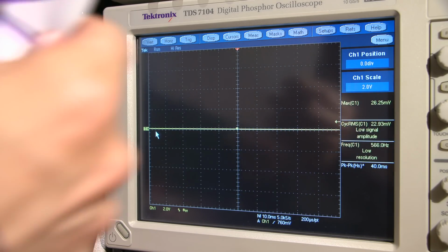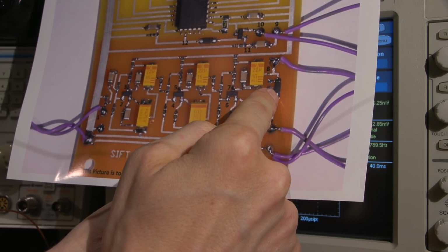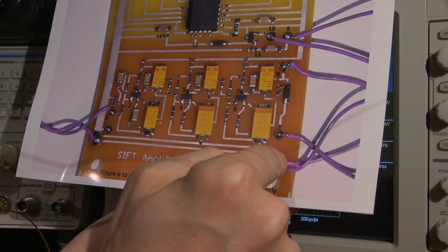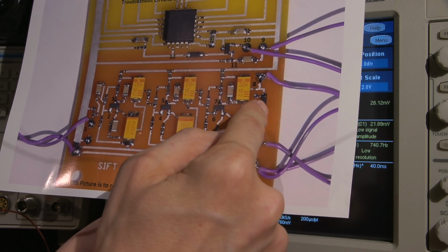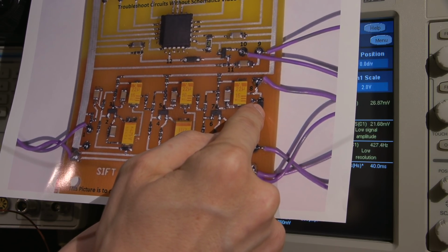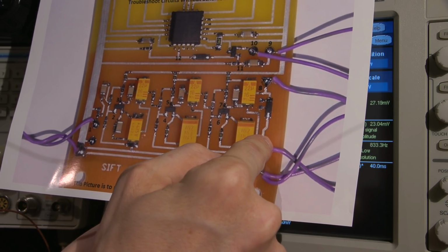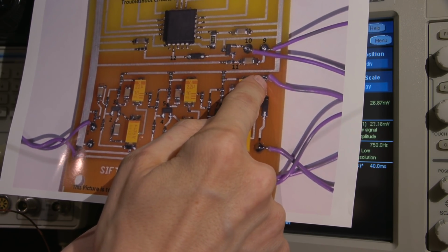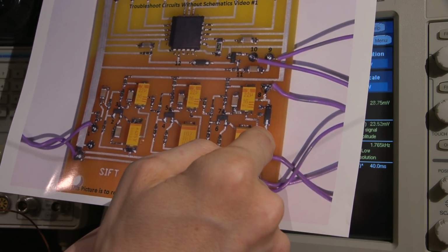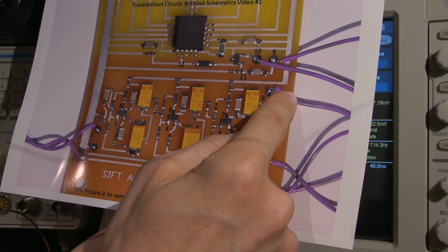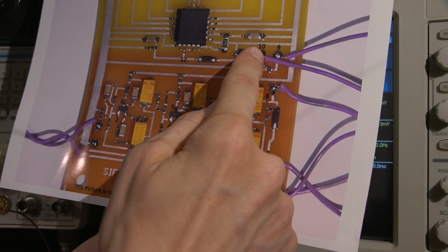we know that we have a diode here that can be switched in and out of circuit, and the back side of the diode is connected to ground or open, just depending on the switch position. You can check the schematic for this as well if this makes things a little bit easier for you. So we know our signal ends up here, so we know that this is going to go to ground and this is just ground, so the only place that the signal can come out at this point is either at 9 or 10. Now, if we follow these leads, we're going to find through the switch that we can either switch this to position 9 here, to test point 9, or to test point 10.